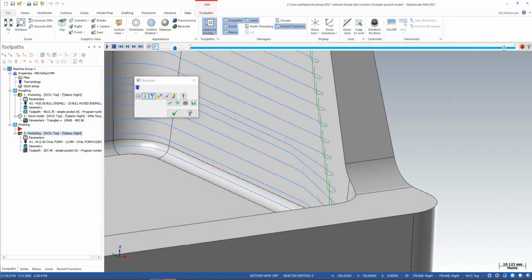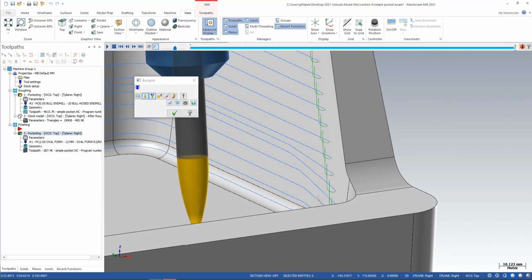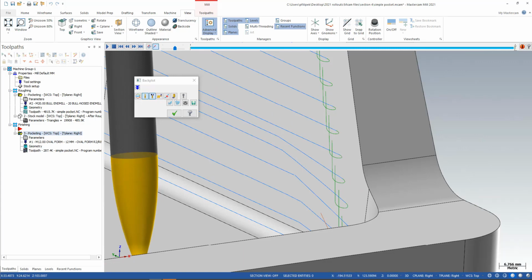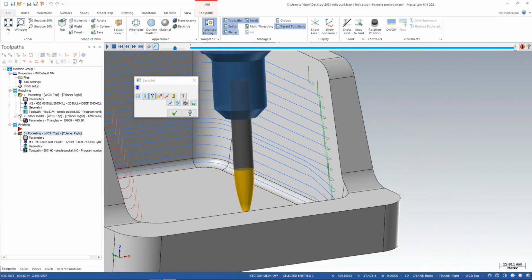Now you will see this here. If I stop this, you see how my step down changed? That's where that tool interference came from with the holder. So it had to start to tilt where it wasn't quite cutting on the same part of that tool. It might have been cutting on a smaller diameter, so maybe 20%.